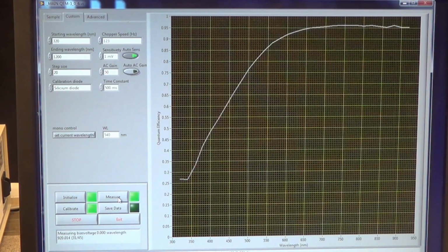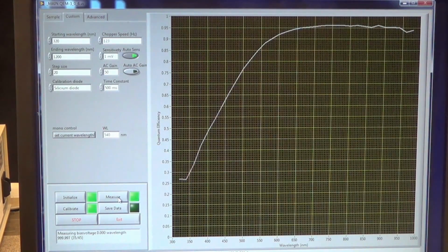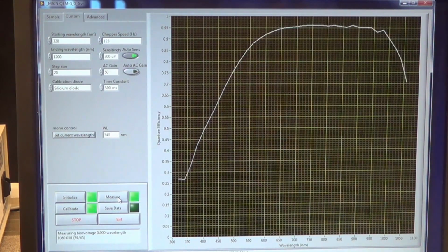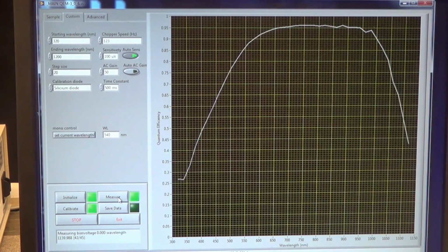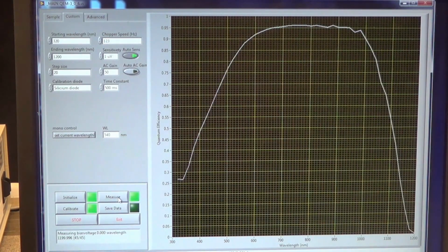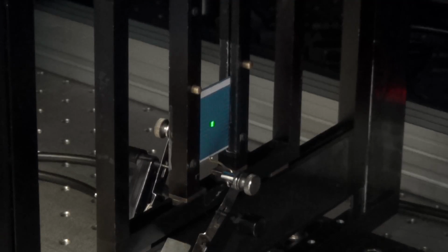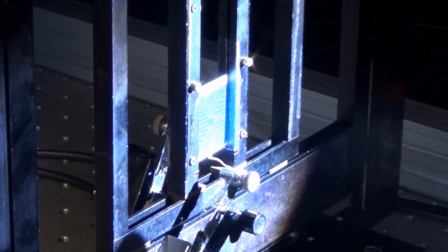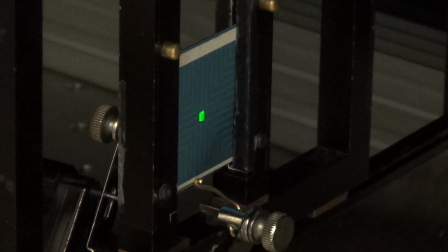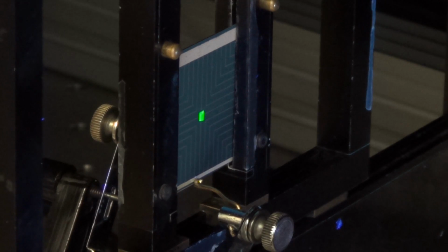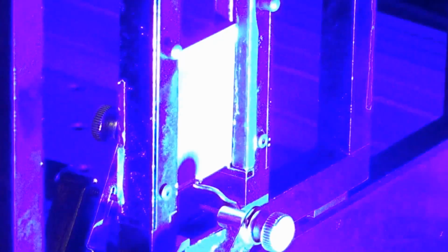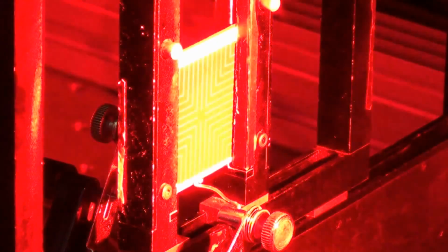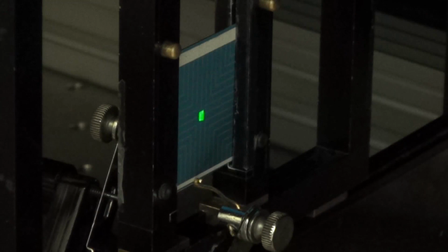The external quantum efficiency of this particular solar cell is above 95% in the mid-range wavelengths. However, there are inevitable reflection and collection losses in the short and long wavelengths, respectively. High-intensity white bias illumination can be applied to simulate operation under one-sun illumination, as was mentioned in the previous video. The bias LED ring further contains the colors ultraviolet, cyan, blue, green, red, deep red and infrared.